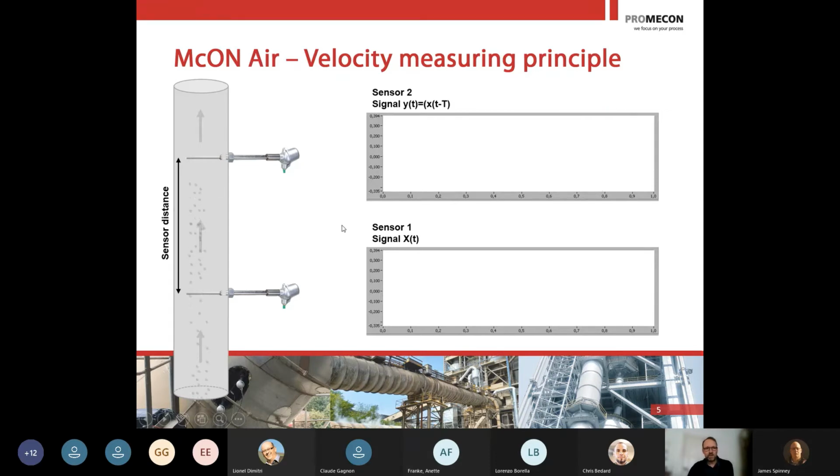And what they do is they are scanning the electrostatic charging, or the electrostatic pattern of the charged dust particles passing the sensors. And the charging comes from, you probably know that all ducts need to be grounded properly if you're transporting dust or any kind of isolating material. And this electrostatic charging comes from particle-to-particle collisions and from collisions to the duct walls.